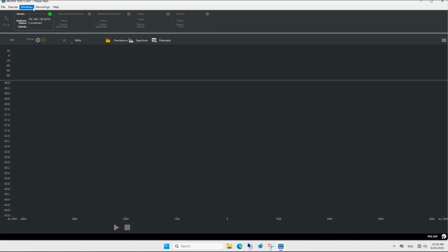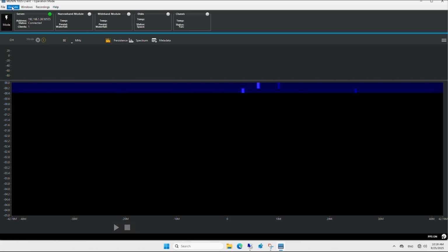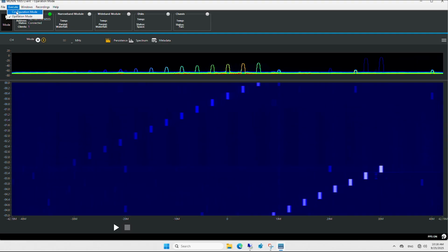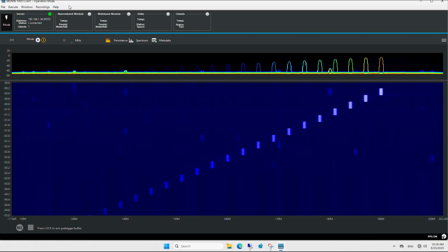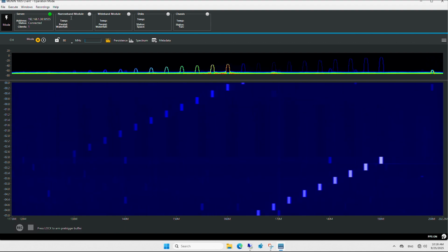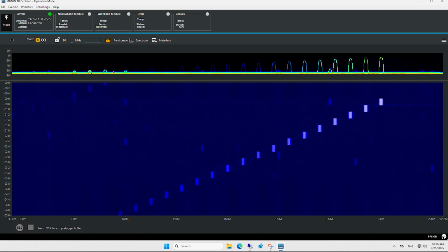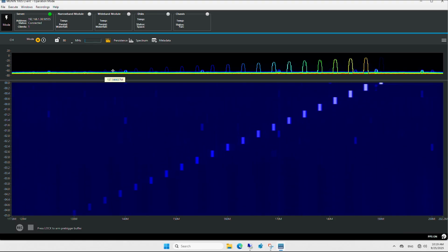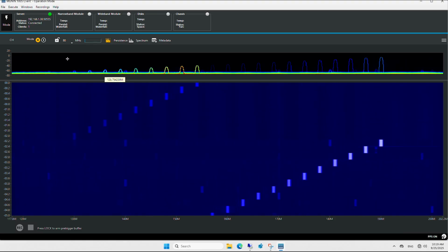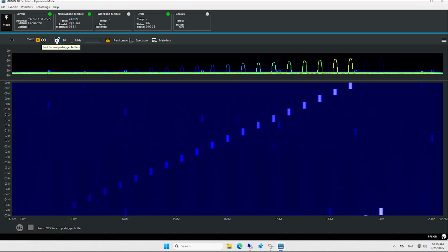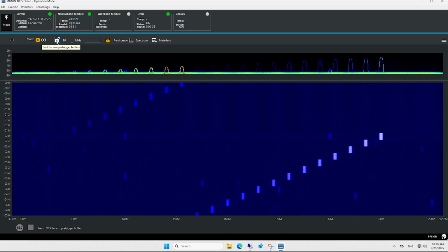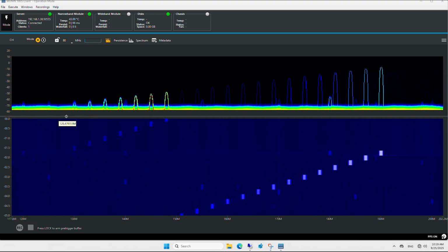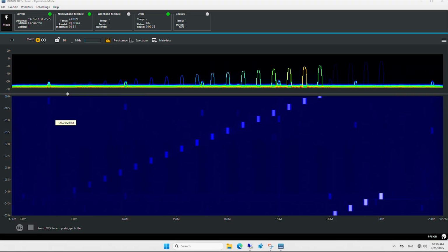Once the client is loaded up, I'll hit execute. Oh, it's already in operation mode. So here we see the system is running, and the sweep in level and power that I configured from my RF signal generator is what we're seeing on screen here. We can see both the spectrum view, and below it the waterfall plot.